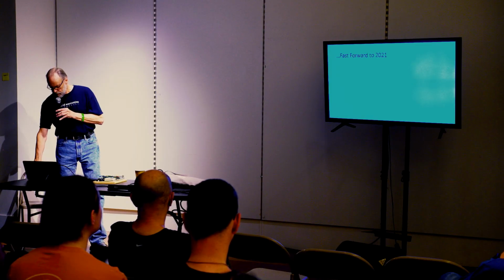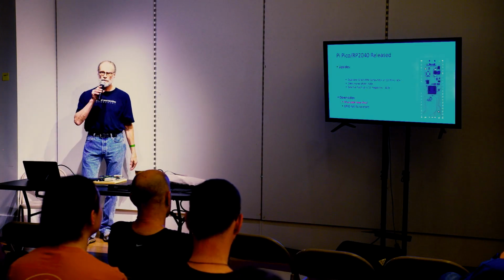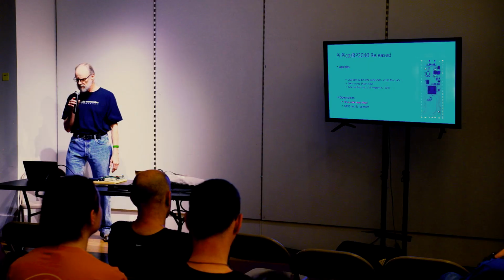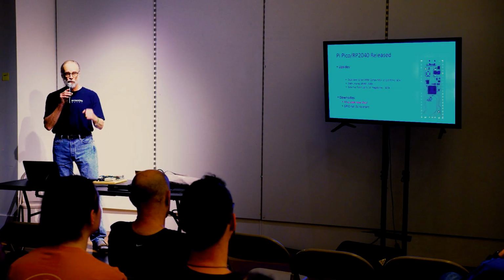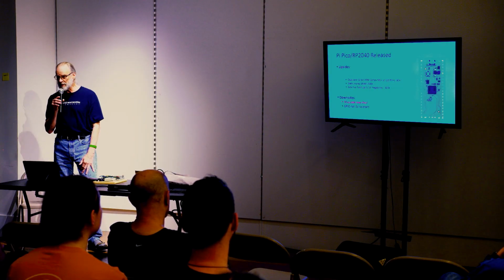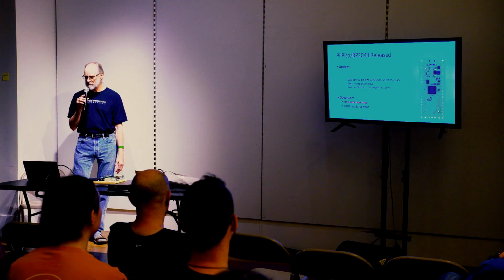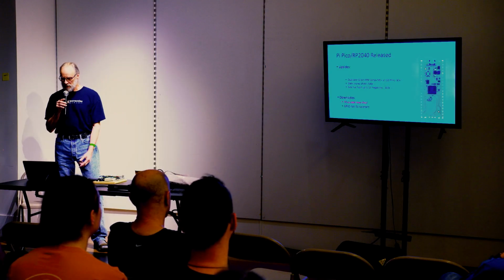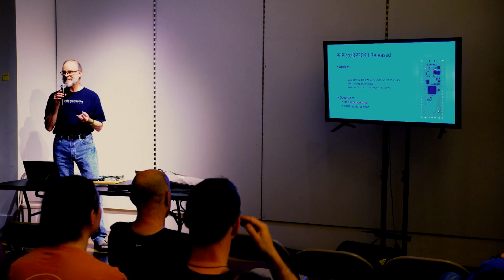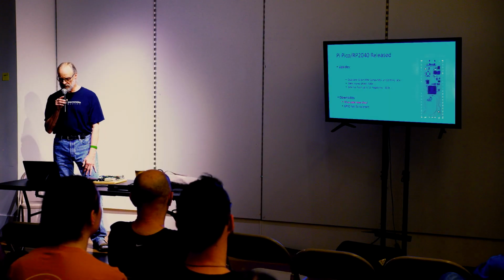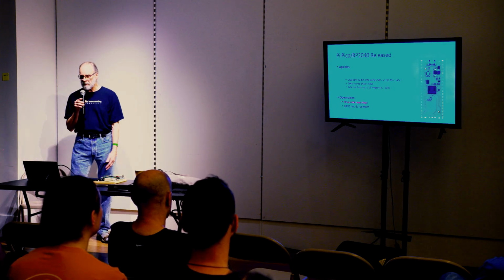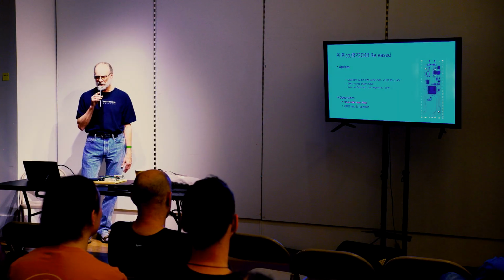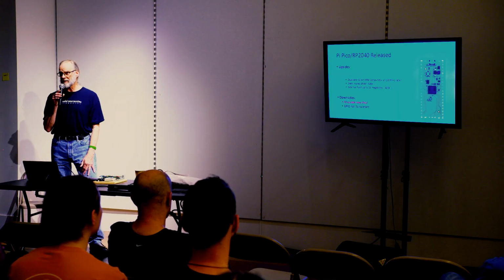So we fast forward to 2021, and I'm sure you're all familiar with this device. It's a cool new chip. Look what Moore's Law has done for us in the years since that HC11 came out in this one. It's got 2 cores, each running 60 times faster than what's going on in the ECU. It's got 500 times the amount of SRAM. It has 500 times the amount of flash. Downsides? Well, it's a cool new chip, and it's not 5-volt tolerant I/O.